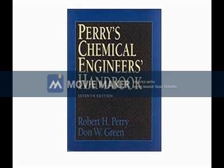Next is the number of transfer units by the equation, that is (y1 minus y2) by (y minus y star) Lm. This equation also you have to learn by heart, or you can find it in Perry. It may be available in Perry. You find the absorption chapter, mark it and take it from there. Otherwise, this is a simple equation you can learn by heart.